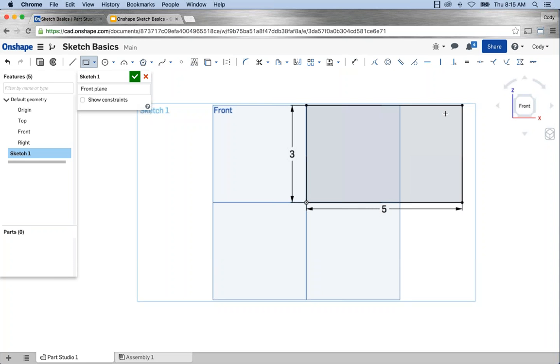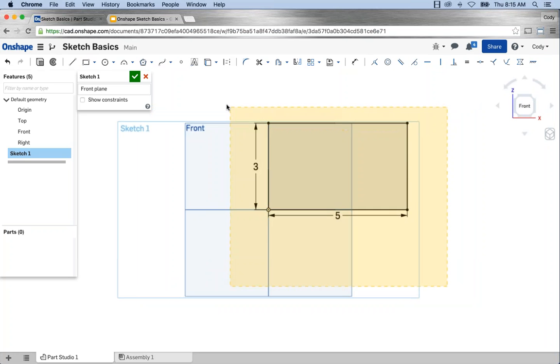So I can sketch a rectangle, enter 5, and that adds a dimension and defines the sketch. So I can very quickly add sketch dimensions if that's the workflow that I like. So, can you add dimensions as you're sketching? The answer is yes. You'll see them appear. Just enter a value, enter, and it defines it. So that is a corner rectangle.